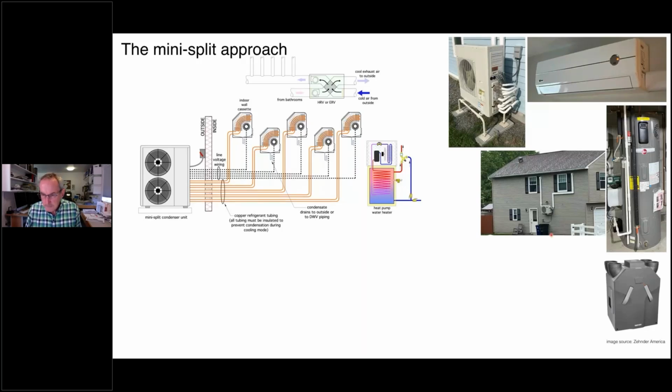And this is an example of a common retrofit of a ductless system where the condenser unit, in this case, is mounted on brackets on the side of the house. And you'll see these plastic channels that route the refrigeration tubing up to wall penetrations that go through to the indoor units. And again, this is just 2 units. If you can imagine, maybe there's another unit over here and so forth. We've seen buildings with upwards of 150 feet of this exterior ducting enclosure system, all fastened to the outside of the building.